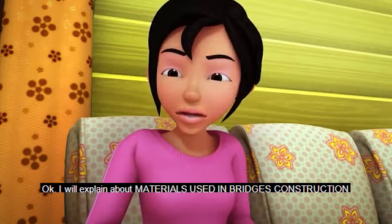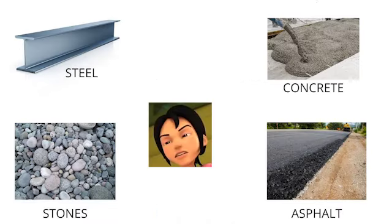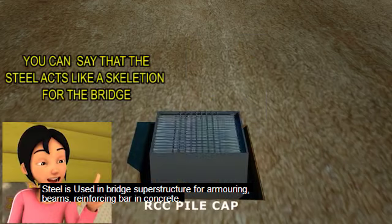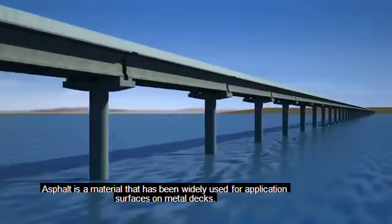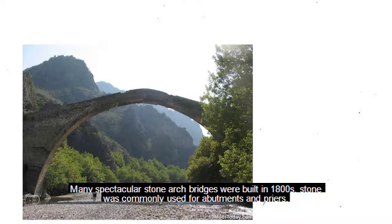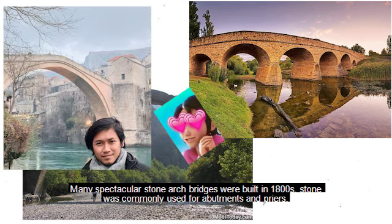Okay, I will explain about material used in bridge construction. Some of the main materials found in bridges are steel, concrete, stone and asphalt. Steel is used in bridge superstructure for armoring, beam, reinforcing bar in concrete. Concrete is commonly used for many members of bridge structures such as deck. Asphalt is a material that has been widely used for application surface of metal deck. Many spectacular stone arch bridges were built in 800. Stone was commonly used for abutment and pier.